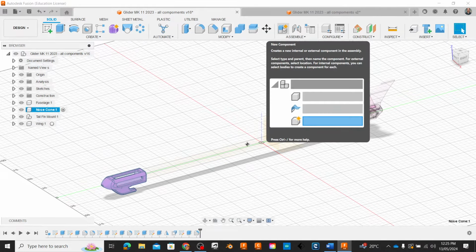I'm going to type in the NACA profile number that I want to have. And it is 0010. And I'm going to take points per side down to about 12. Probably do a max of 20 if you want to. It doesn't really matter. You don't want it to be anything over 20. So I did 12 here before. I might try 15 this time. It doesn't really matter.